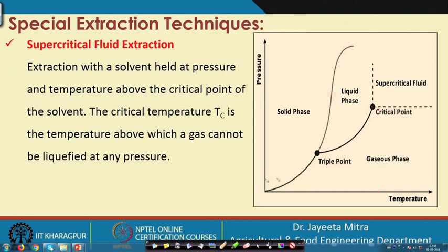However, liquids do not change their density much over pressure. So, in a moderate pressure range or at atmospheric pressure, they are independent of pressure. When the gas is exposed to higher pressure, beyond a certain limit its density becomes higher, reaching almost towards the density of a liquid.